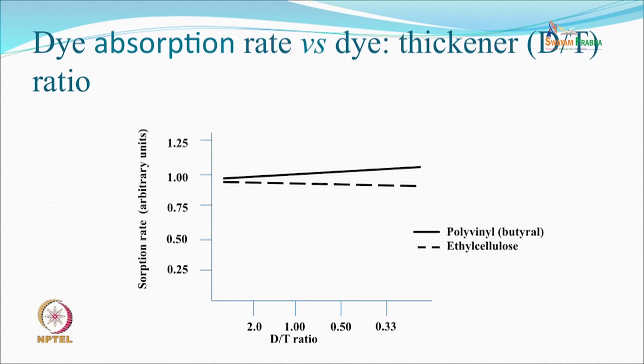So when you do a print which may have different shades, where the dye may be very low or very high, you will still have the transfer, if the transfer rate is the same. If the transfer rate becomes very different, then with the time of transfer kept fixed, 30 seconds or whatever, the expected tones which are supposed to be on the paper may not get transferred in exactly the manner you would have expected, because the rate of transfer may be different, and therefore the time required for a complete transfer may be different, and so things can change.